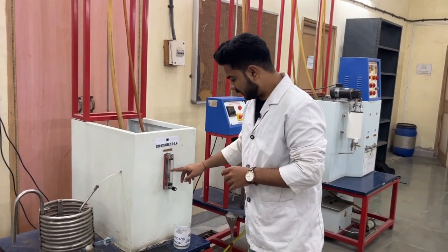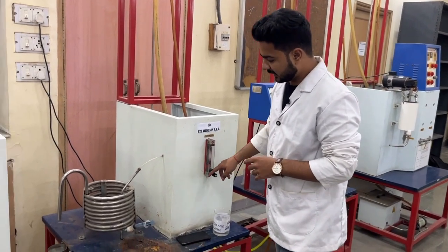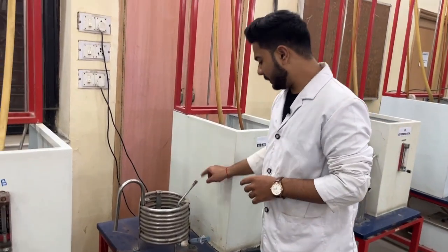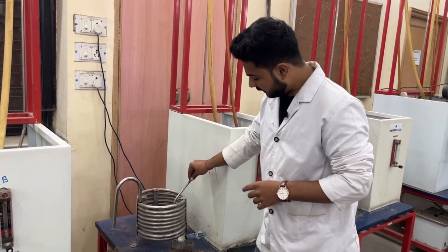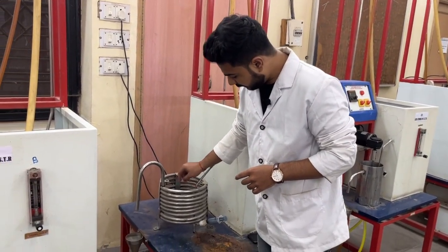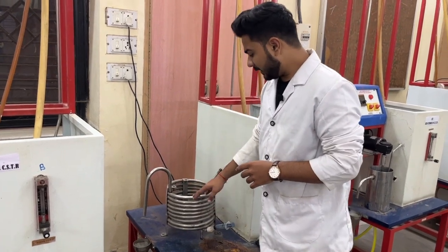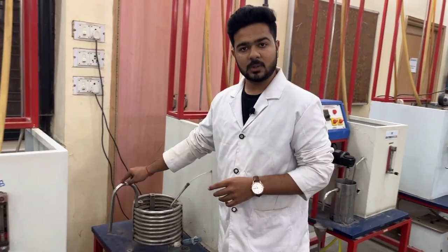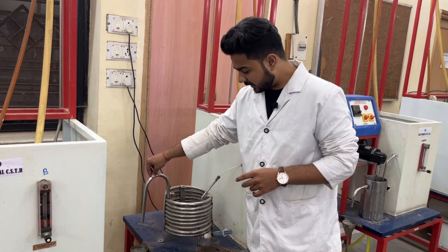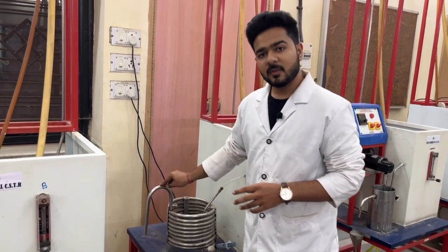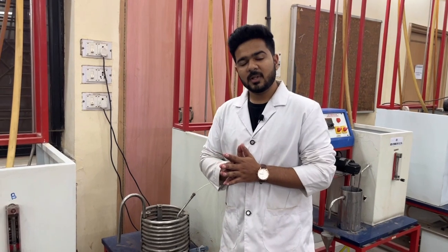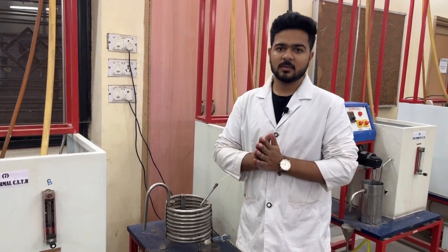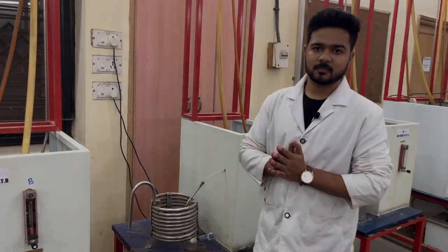After we set the flow rate, the liquid will start flowing from the rotameter to the PFR inlet. The liquid will start flowing through the tubes and we will wait for the liquid to come out from the outlet. As soon as the liquid comes out from the outlet, we will wait for the reactor to attain its steady state. In this experiment, we will wait for around 8 minutes for the steady state to be attained.